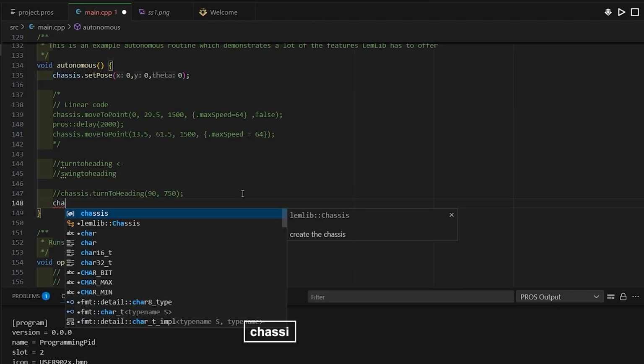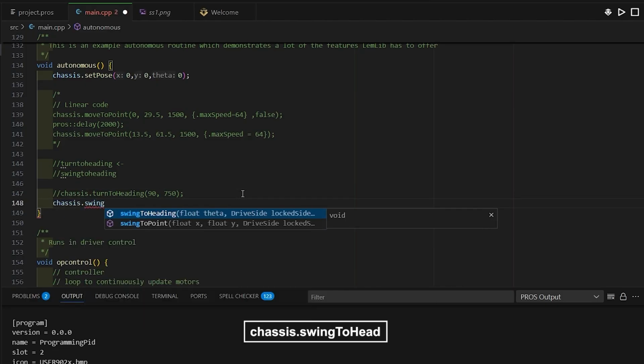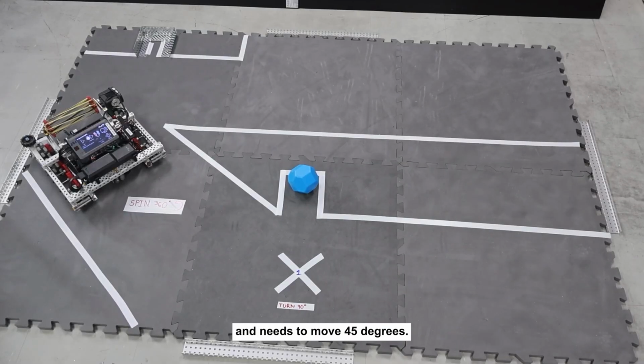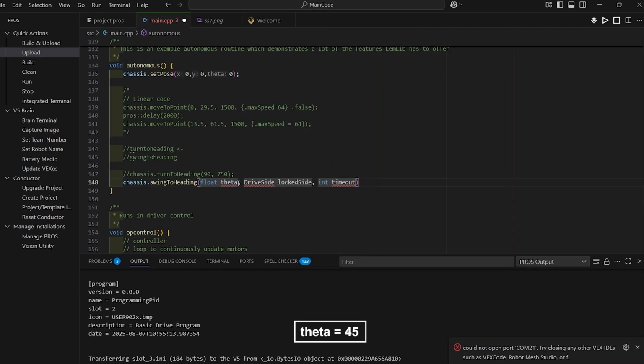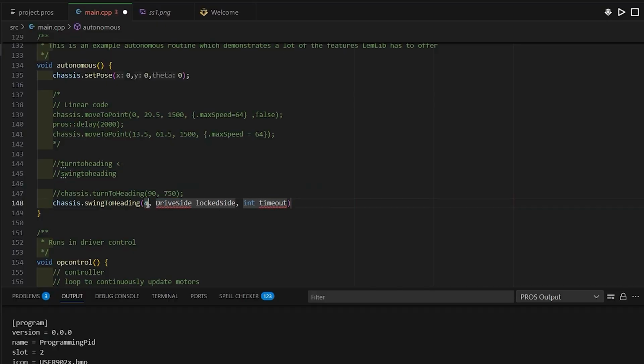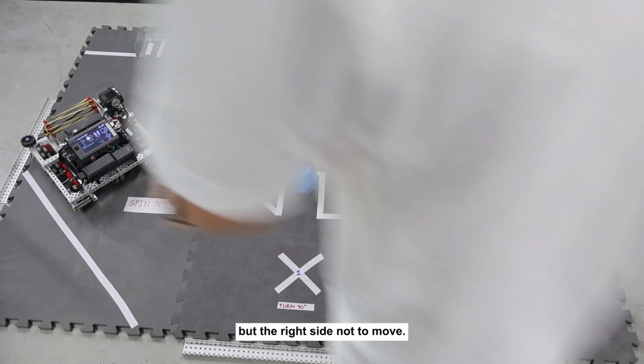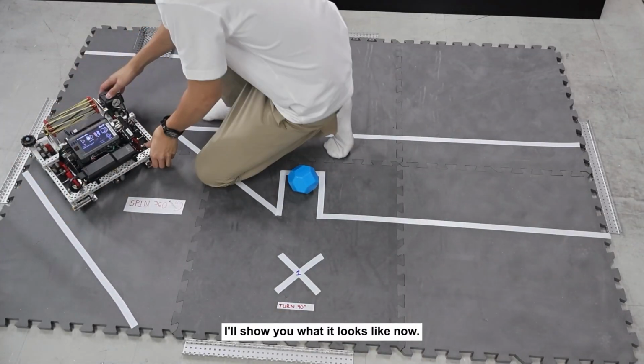So we'll do chassis.swing to heading, and then if we go back to our robot right now, it needs to move 45 degrees. So we'll put theta to 45, and then the drive side, lock side would be right, because if we look at the robot here, when we're turning, we want the left side to move, but the right side not to move. I'll show you what it looks like now.